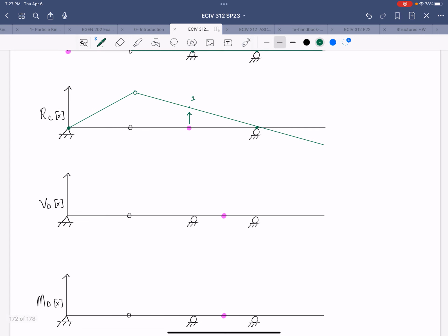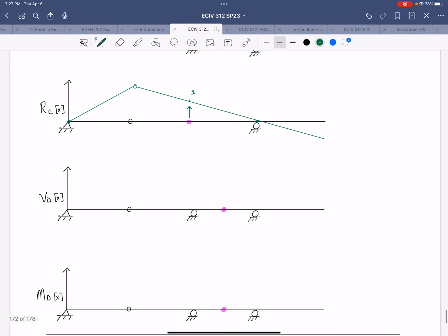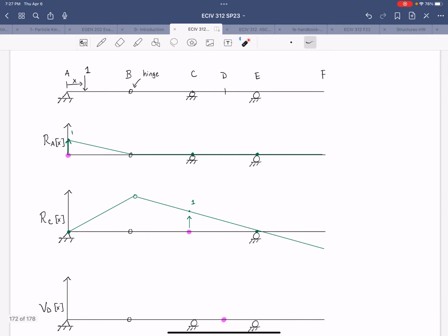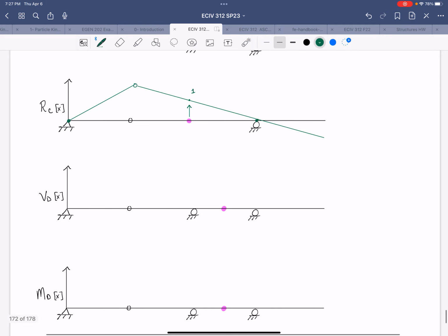Next up, we have the shear at D. So we've identified the location of interest, right? D is halfway between C and E, or it looks like it is anyway. When we put numbers to it, we'll find that it is. And we're going to cut the beam, insert that roller guide, and force the right side up and the left side down.